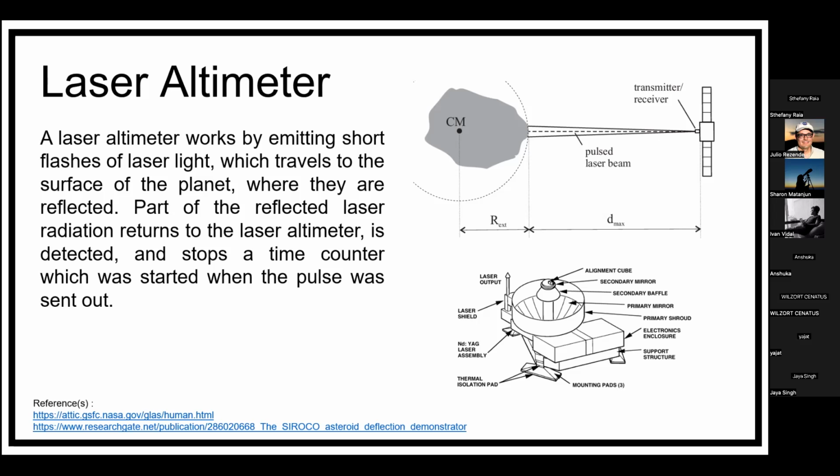A laser altimeter operates in a very similar way to radar technology, which uses radio frequency pulses instead of light pulses. An optical telescope is used to collect the received reflected laser pulse photons onto a photodiode. And the repeated measurements over consecutive orbits are used to understand the morphology of the planetary surfaces and the construction of precise topography maps.